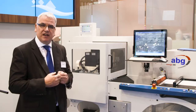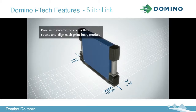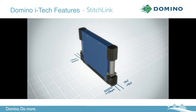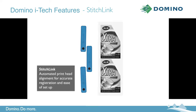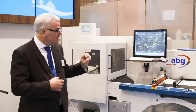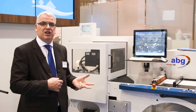Finally, we have Stitch Link. Stitch Link is our micro motor controller system that enables us to align the three modules or the multiple modules, depending on the part width we have within the K600i. Because if they're not aligned, then we'll tend to get white lines formed between the modules. So it's a highly precise process, so we can align those modules in two different axes to give optimum print quality, less operator involvement, and reduced risk of product rejects. So, intelligent technology from Domino: Clean Cap, Active Flow, and Stitch Link.